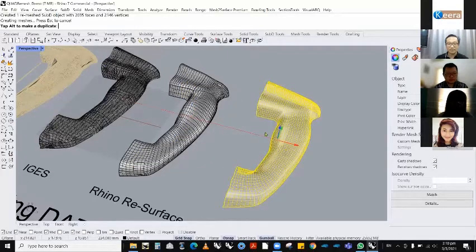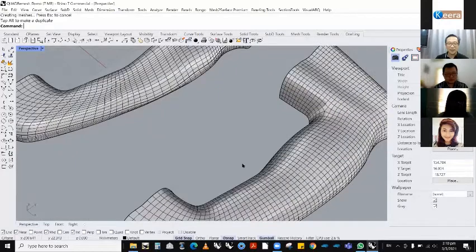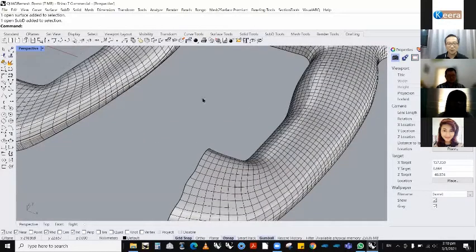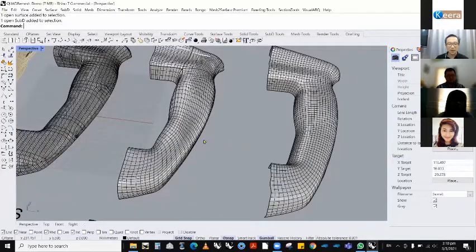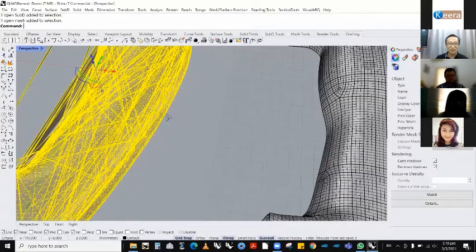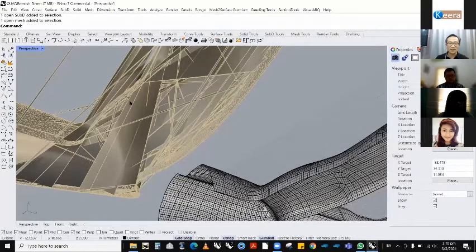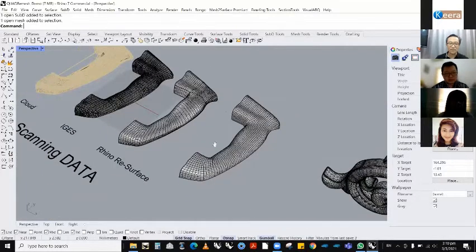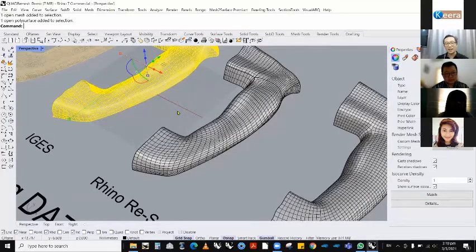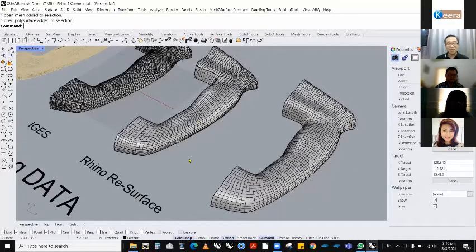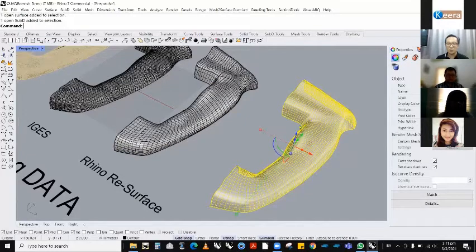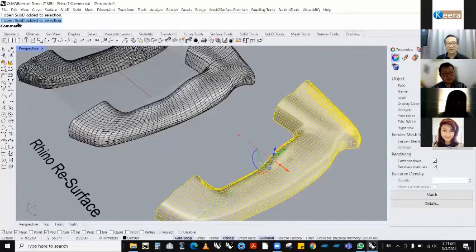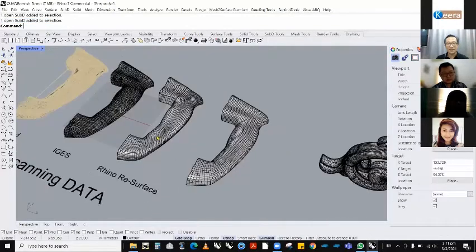So this was the Rhino resurfacing that we did. This is the new SubD division surface that we got. I'm not going into all the details. I just want to show you that I could probably skip this step next time and go straight to this. I tried using this, but of course my information is such a mess, so I would rather not work on this unless I have a very clean mesh file. However, what I did was work from this part where the file was cleaner after the post-processing. Rhino is fine for sure, but SubD will probably help me do more. How would I know that this is SubD? The moment I pick this, it says on the Rhino screen that one SubD is added to my selection. So that's my SubD example from scan data.